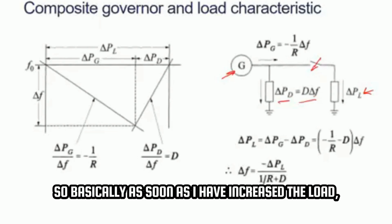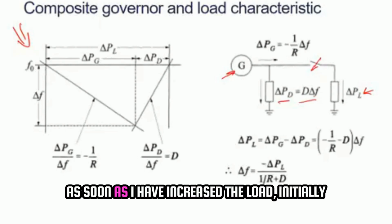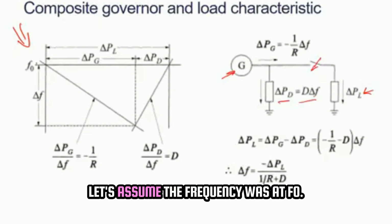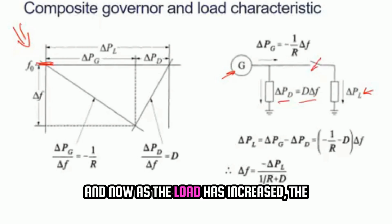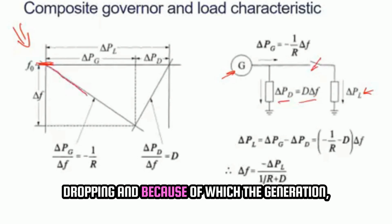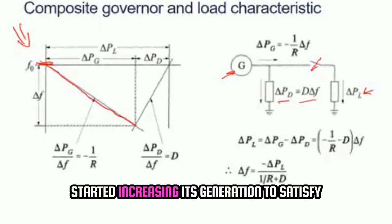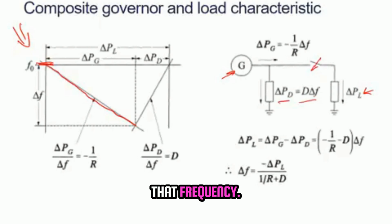So basically, as soon as I have increased the load, see the left hand of this diagram. Initially let's assume the frequency was at F0, and now as the load has increased, the frequency from the generator has started dropping, because of which the generation, based on its droop characteristics, has started increasing to satisfy that frequency.